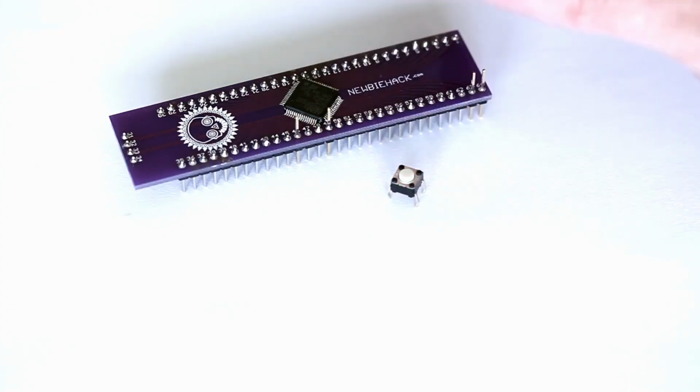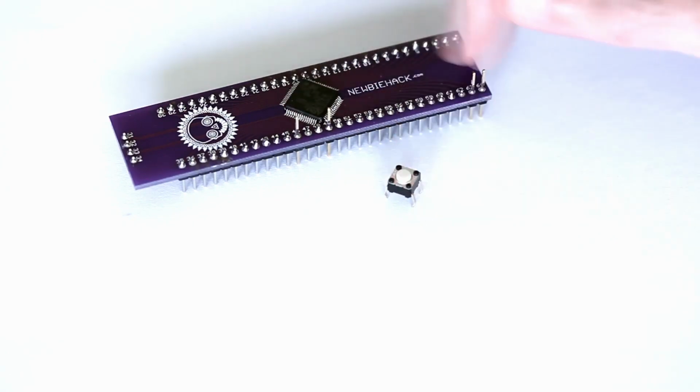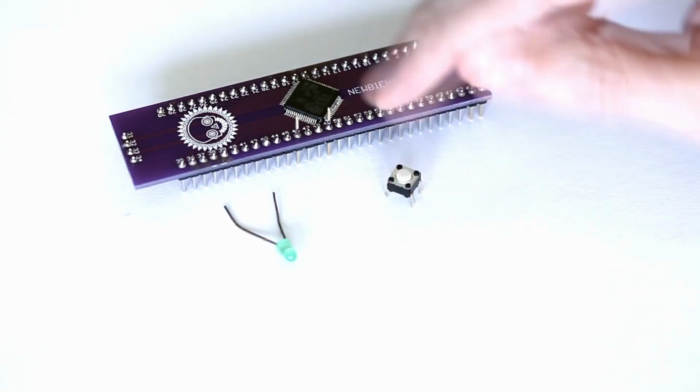We'll take a look at using the GPIO, the general purpose input-output, and we'll take a look at the input side of things. Using a push button connected to one of the GPIO pins, and then we'll output to an LED. We'll take a push button switch like this. We'll have the microcontroller read the push button switch on one of the GPIO pins, and then we'll output on another pin, completely different port and completely different pin, on an LED. When we press the button, the LED will turn on.